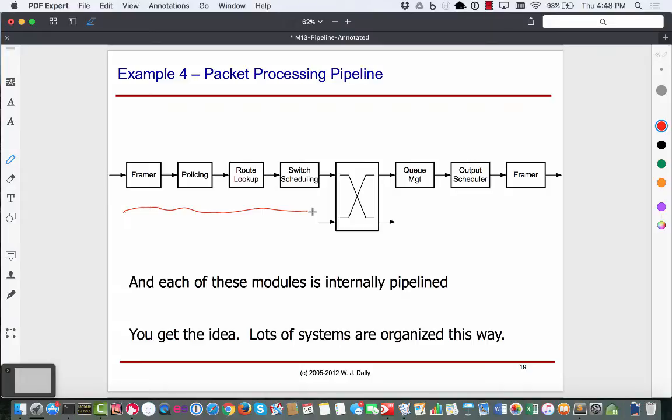There was a Piazza comment about why we bother with things like FPGAs. Why not our good old microcontrollers and Arduino? The performance levels are dramatically different. The point to note is your processor does, in a single clock cycle, a logic operation, an AND. Your FPGA in that same clock cycle can do millions or tens of thousands of ANDs. So the potential is there because all that stuff is sitting there ready to work in parallel.